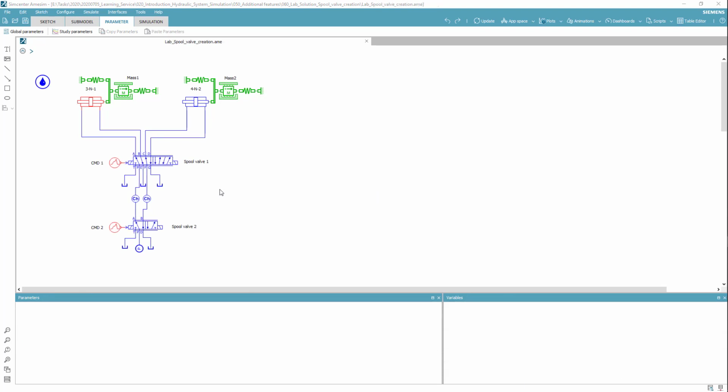We can now connect the spool valves to gear shift cylinders. Due to causality issues, you might need 2 capacitive elements such as chambers between 2 ports. We use a pressure source of constant 2 bar to represent the hydraulic pump in ideal case. Can you figure out how to set the command profiles of both valves so that we can have sequential gear shifts in one simulation run?